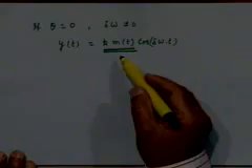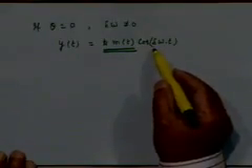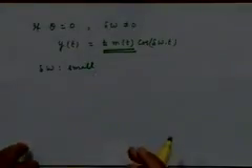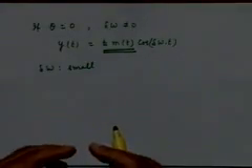And in that case, basically what you see is that cosine delta omega t will be a slowly varying sine wave multiplying your m of t, right. This delta omega is very low frequency here, so delta omega is typically small, right. So what will you see? You will see that your incoming signal is multiplied by a scaling factor, which is sometimes going up and sometimes reducing significantly, right.